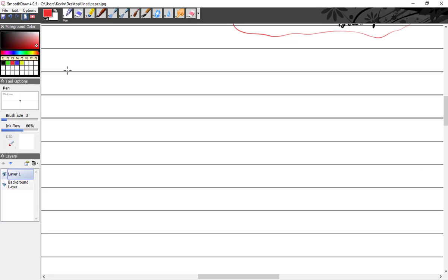Did I write... I'm looking for my notes. I think I already wrote Kettering. I also put, also known as a battery ignition. All right. So I put B, used on older cars. Did I put C, principle of operation? Yes. So this is now just under I. Under principles of operation, battery supplies 12 volts to a primary coil. What is wrong with that statement?